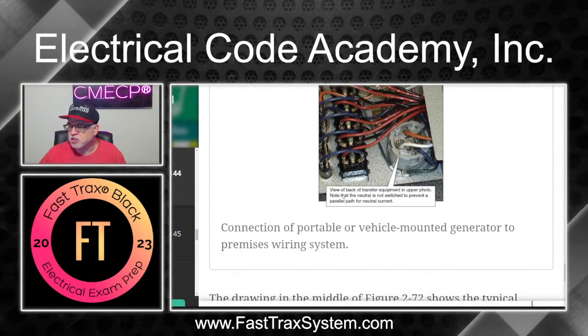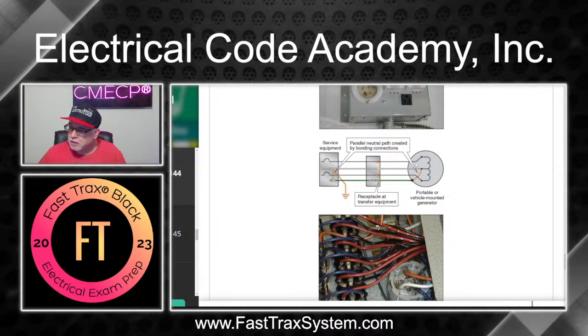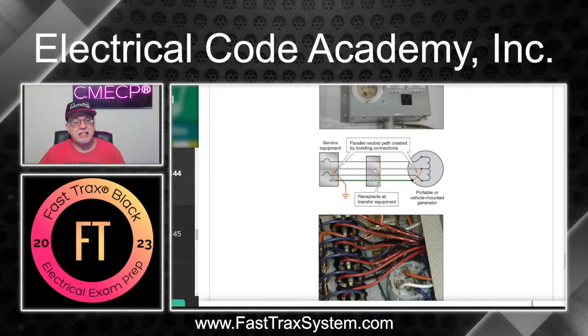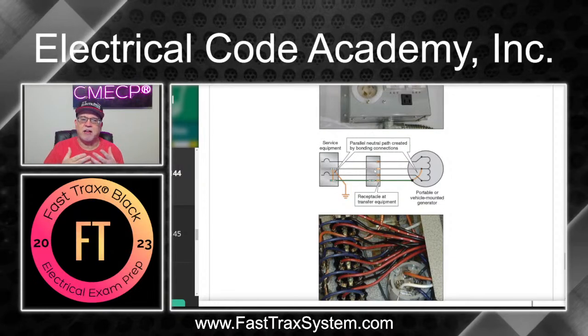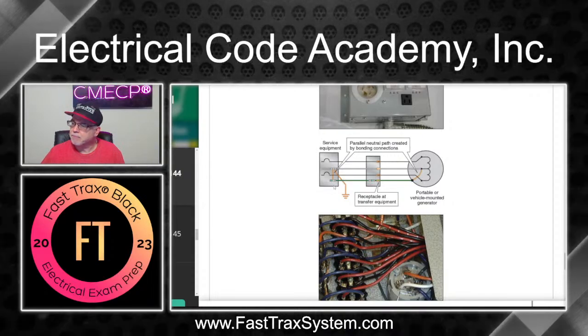But okay, just be careful and realize that if you're going to use a generator that has the neutral connected to the frame, which is what you would use in a standalone, and you're going to use it in this scenario, you need to what? You need to switch the neutral. And the sad thing is, when you're buying transfer equipment, it doesn't necessarily always come with the generator. So you've got to be careful what you buy. You've got to know what you're buying. And again, you can create a serious issue if you don't know what you're buying, okay?